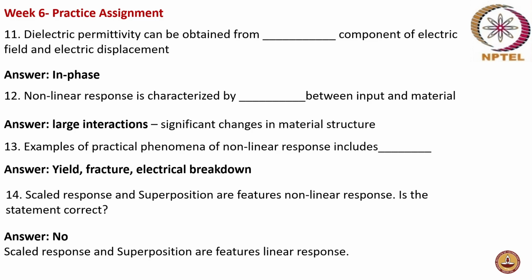Okay, and similarly with time-temperature superposition, for example, instead of doing it for 100 hours together, if you do it at a higher temperature, you get some response of the material, some modulus of the material. If you cannot afford 100 hours, you can apply some small amount of strain, and see what the stress response is, so that you can identify it by doing it at 40 degrees for a much shorter time.